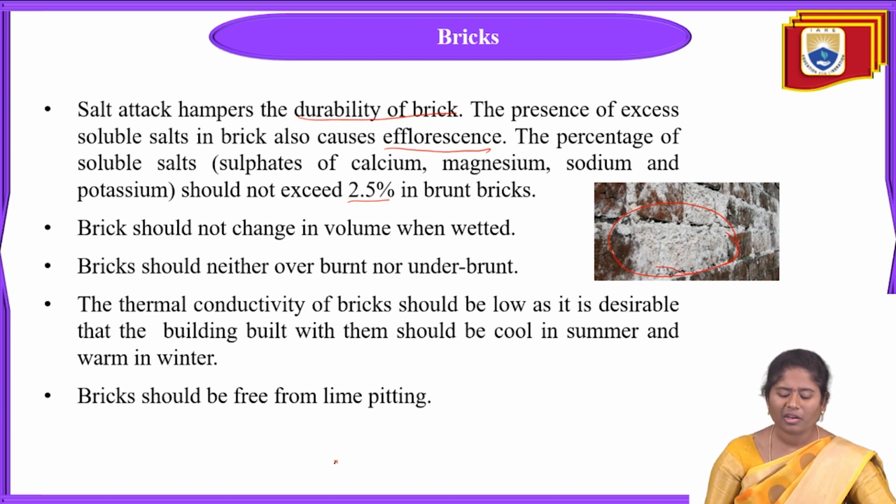Next, the thermal conductivity of the brick should also be very low, because it is desirable that a building built with them should be cool in summer and warm in winter. That's why bricks should have very low thermal conductivity.